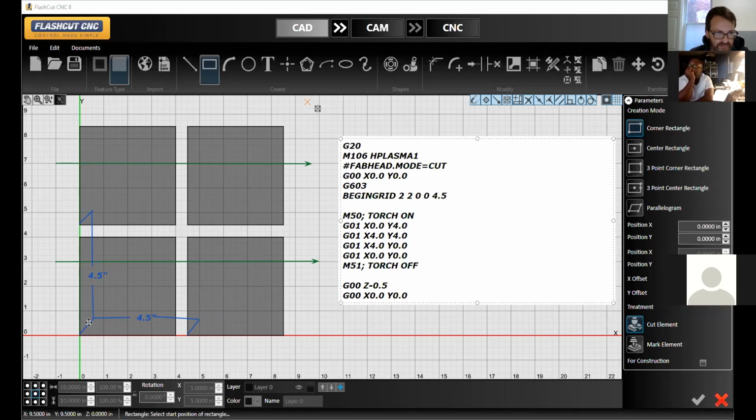And that applies with the Y direction as well. If we made it 4 inches, these blocks are going to be on top of each other. So from the bottom corner of your first part to the bottom corner of the next part in the Y direction, we need that to be beyond 4 inches. So we're also going to make that 4.5.